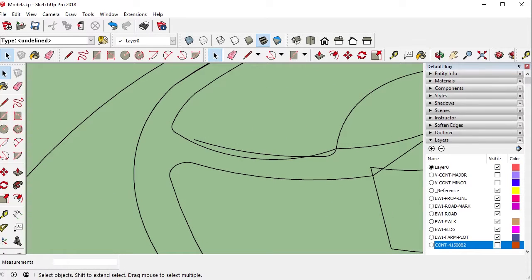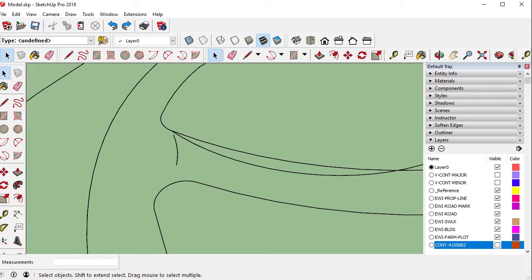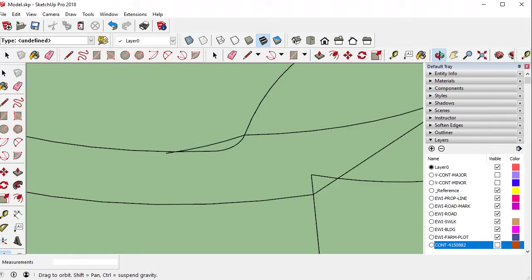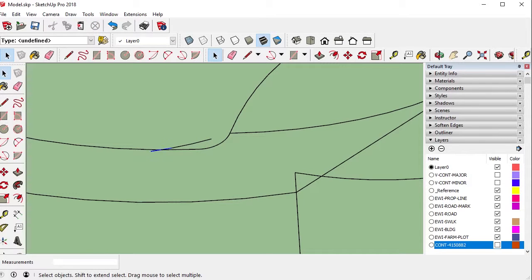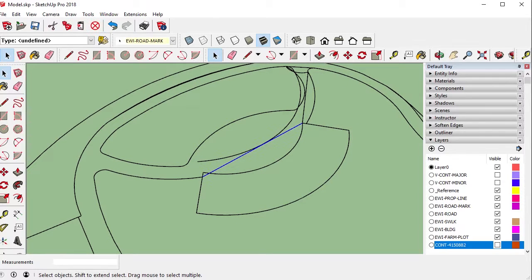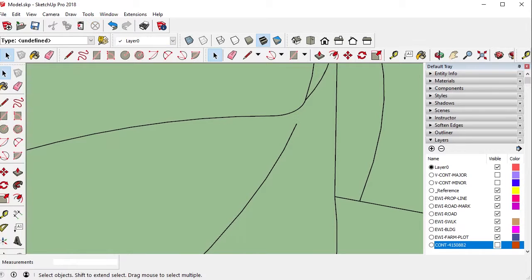I probably needed, it's probably that line was the correct line. So I'm going to undo that. That was the correct line. So I'll delete that. When you double click on an object, it will delete that object completely. So triple click. We'll select the rest of that line. So it's a little bit of work here. It definitely is faster in CAD than SketchUp. SketchUp is not a CAD program. It does modeling, but it's really not a very good CAD program. So I'll be back.